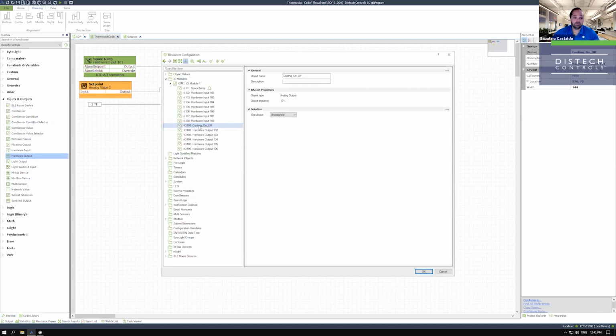And again, we go into its interpretation and say, what kind of output are we using? So this is a universal output. It's the kind of I/O board we added earlier. It was the 8UI6UO. So we could do digital output. We could do pulse width modulation, 0 to 10 volts DC, or 0 to 20 milliamps.